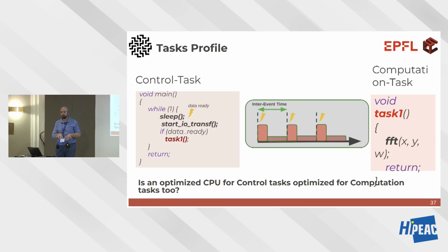Okay. If I'm a sensor and I need to be reactive and in a domain that is always on, I cannot switch off because I'm the sensor itself, for example. And of course you can do power gating only on the CPU, but power gating is expensive. It's difficult to design, takes area. Yeah? It's not always possible or convenient to do it.